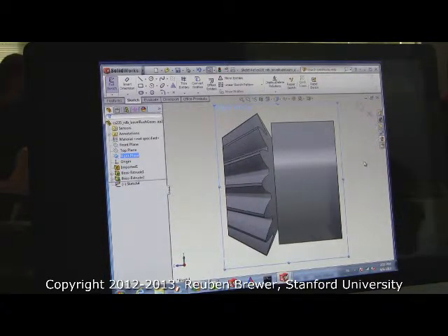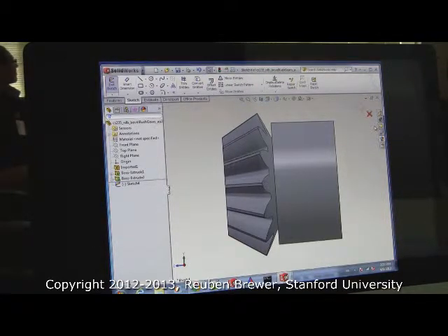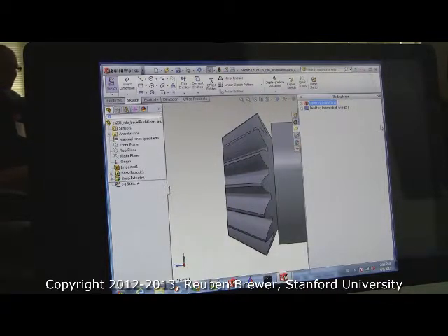It's not letting me extrude that face. So what's happened here is it kicked you out of the extrude. So you select the sketch and you hit that button. See? All that happened was that it kicked you out. So everybody, if you think that you have made a sketch that's good, and you see a sketch on the left-hand side of your screen, but there's no extrusion, it kicked you out for some reason. So just select your sketch, hit extrude, and it'll do it for you.